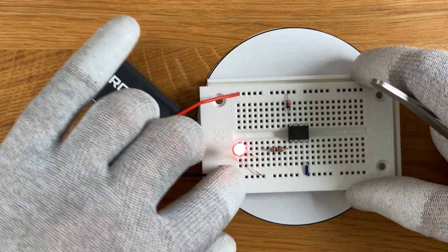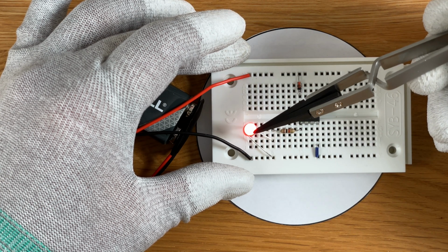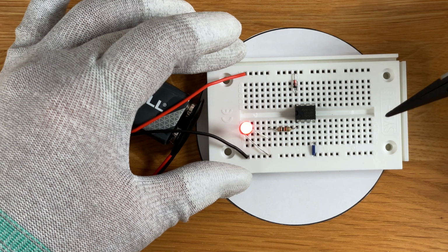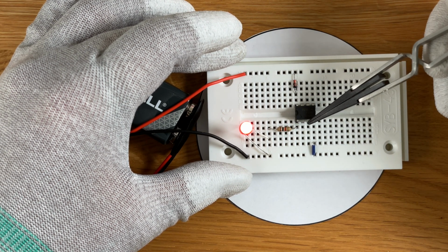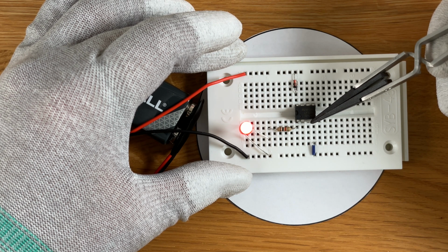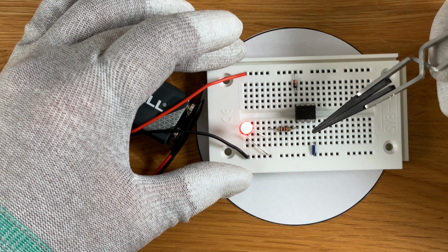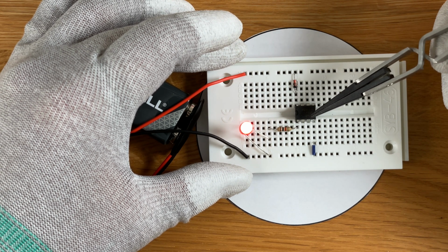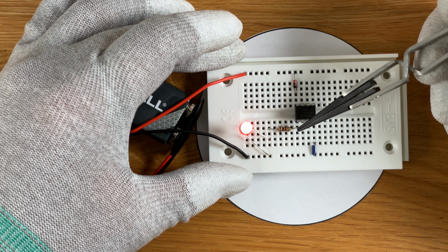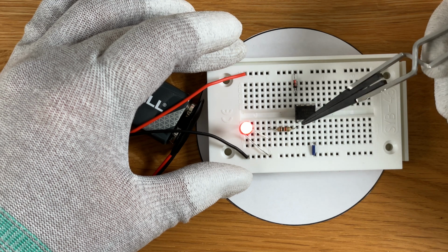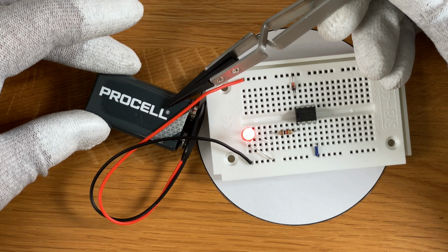And as you can see, as soon as I connect the negative terminal of the battery to the lower power rail, the LED lights up. The reason why this is the case is that this operational amplifier has a significant gain. This means even minute differences between the two entrances are amplified by a factor of 10 to the power of 5, 10 to the power of 6. So a very small difference already brings this operational amplifier and its output into saturation, which means it outputs the maximum amount of power it can output, or the maximum voltage, and this is limited by the supply voltage, in this case 9 volts from the battery.